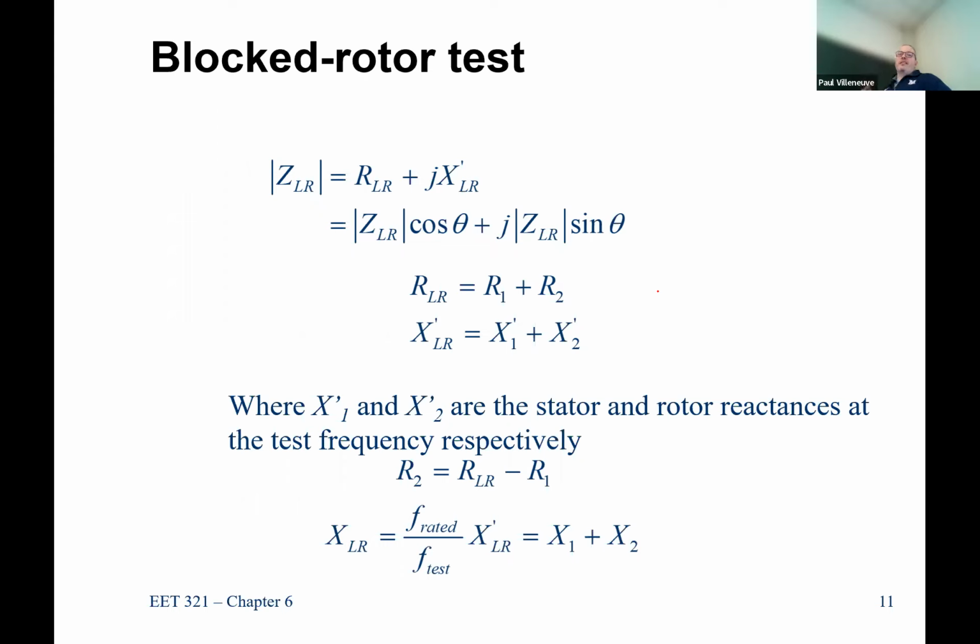Now, here's one thing to keep in mind. When I'm running a machine where the shaft is locked, you remember when we were in lab, or for those of you who did it in TV land, when we ran it at as high a load, what happened to those induction motors in lab? They didn't spin very well, did they? They sounded like they were dying, making a lot of noise, and they didn't sound healthy, which is exactly right. Putting those machines in those conditions is not particularly healthy for them. So you can't run those for long.